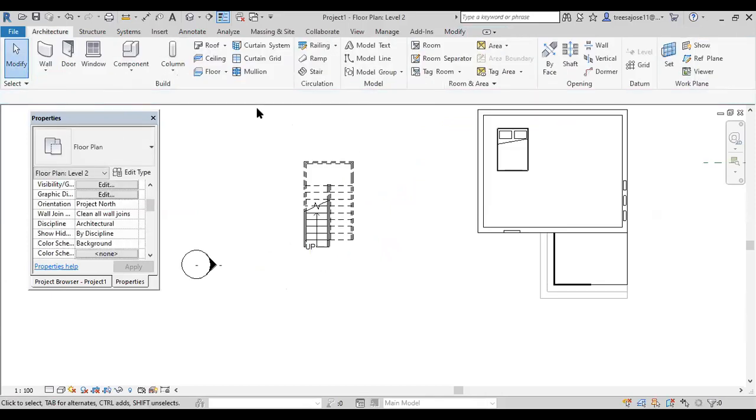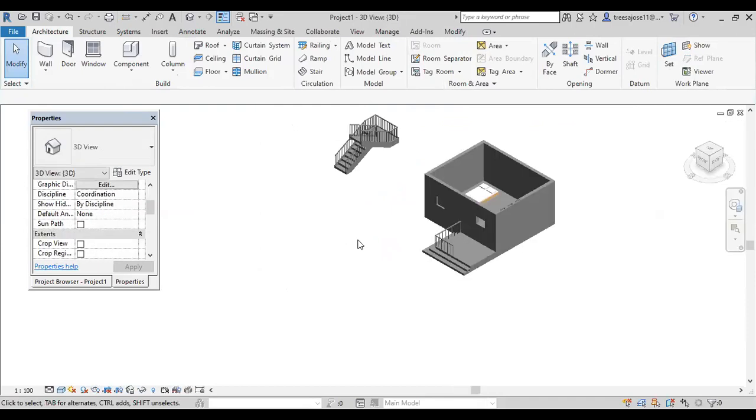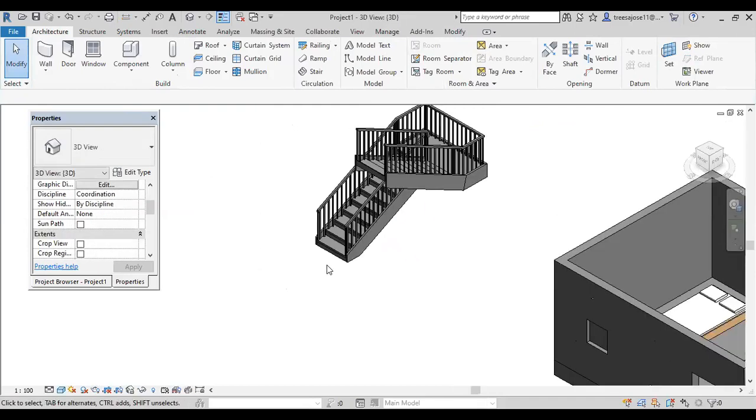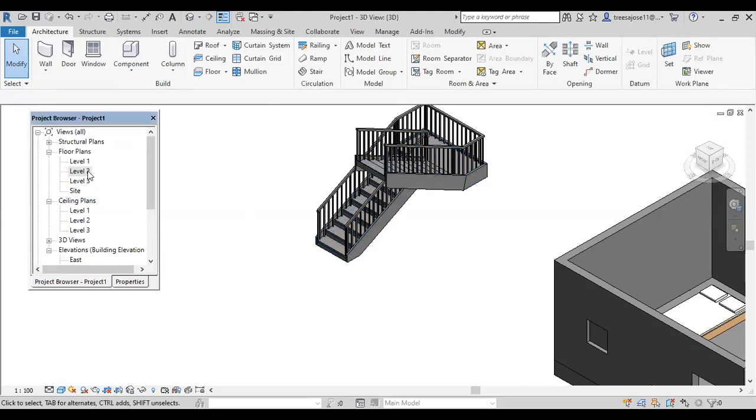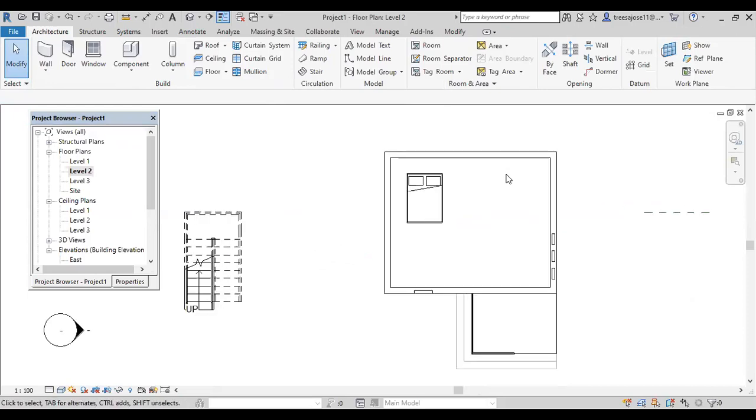Okay. Then if you go to the 3D view, the stair will be generated automatically. And actually better you plan in such a way that, for example, 30, I need 10 steps. I think better you create a model line while you are creating the steps in the plan. For example, we need to generate a step somewhere here. Better you create some reference lines.